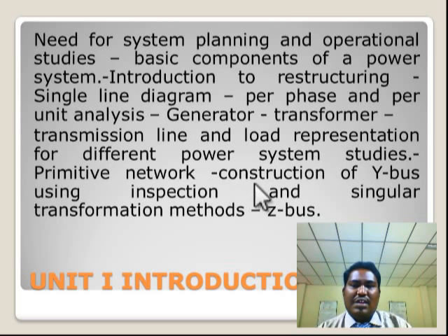And how do we construct the Y bus? Y bus is nothing but the admittance bus. There are two kinds of Y bus evaluation available. One is with the help of inspection, which involves basic circuit theory. With the help of inspection, we may construct our Y bus, or with the help of the singular transformation method, which is a sort of algorithm, or we may construct the Z bus. Z bus is nothing but the impedance bus. So the impedance bus algorithm is also essential for your per unit analysis. We move on to the next slide.